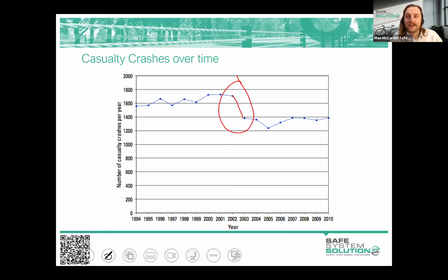The reason we make a note of that is safe system assessments tend to be very project focused, which is excellent, and just maximizing the safety benefits associated with that specific project. But in order to see more of these step changes heading closer towards zero, we do need to also be advocating for speeds that are more forgiving and more survivable, where we do have higher incidence of pedestrian or vulnerable road user activity.